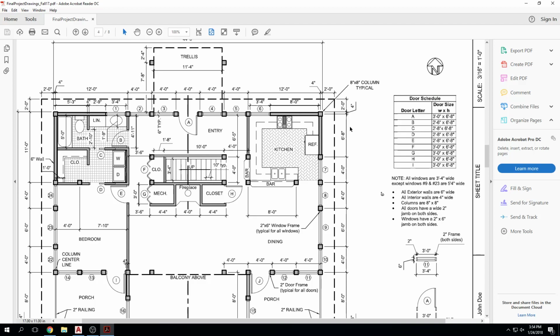So somehow in AutoCAD we have to represent that, right? We have to be able to assign a very thick pen weight to walls, and we have to be able to assign a very thin pen weight to floor finishes, okay? And that is how we're going to use what's called layers in AutoCAD. That's the most important function of layers in AutoCAD, to assign that pen thickness to items, okay?